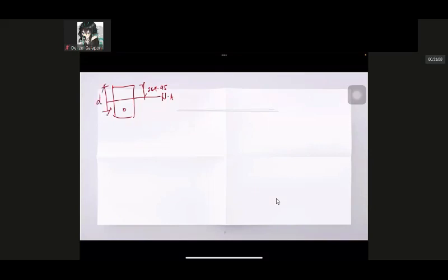So next step is we have to solve the moment of inertia about the neutral axis. And the moment of inertia about the neutral axis is equal to the summation of the original moment of inertia plus area times the distance from the centroid of the original area to the neutral axis squared, di ba?